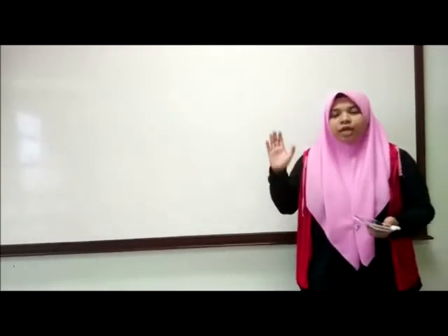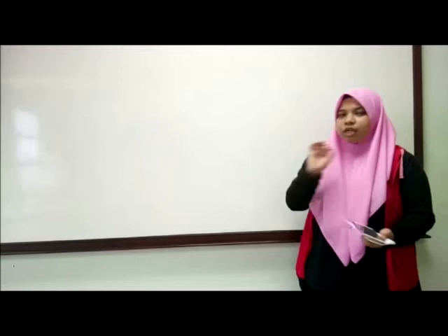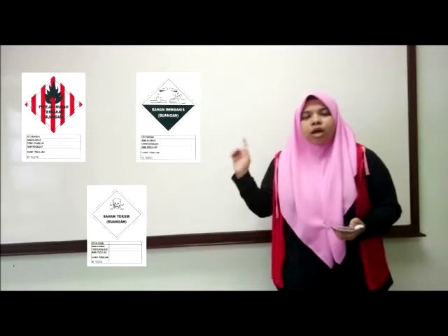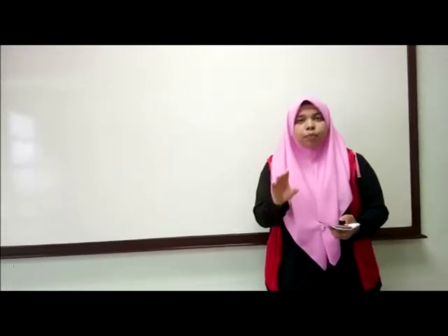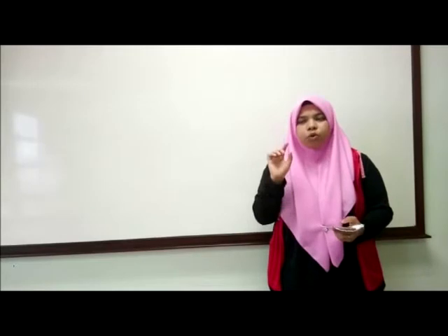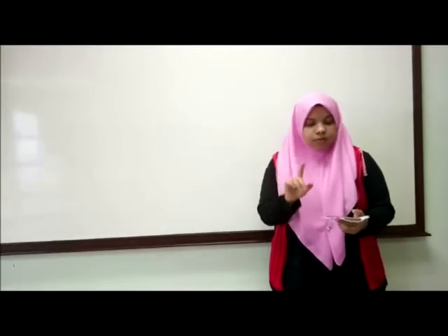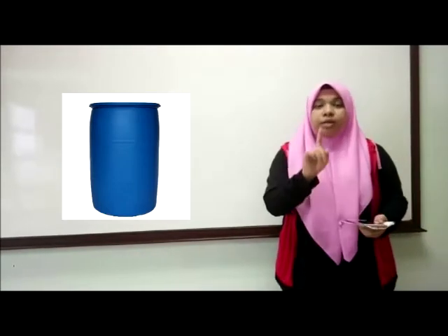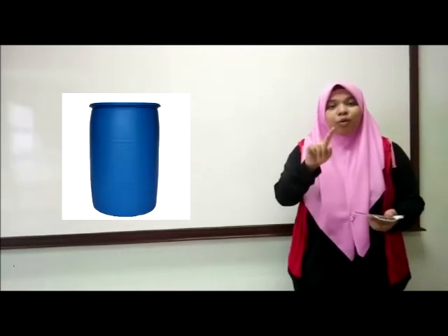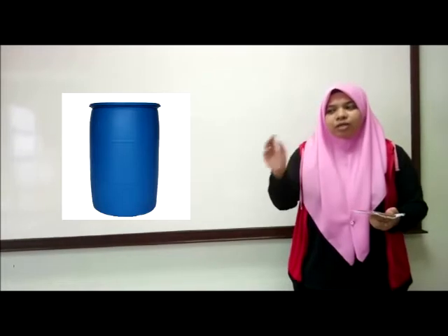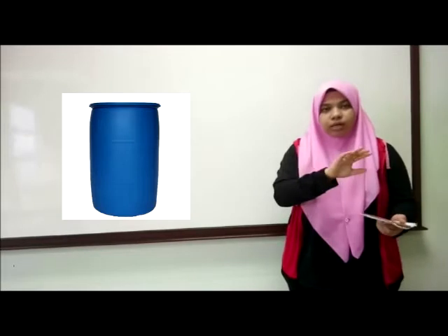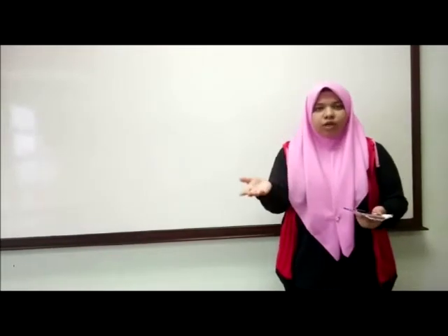So the hazard levels involved in spent solvent are flammable, corrosive, and toxic. The container that can be used to store the spent solvent is a bunghole drum, which is made from plastic, because you cannot use steel, as the steel will react with the metal inside the spent solvent.